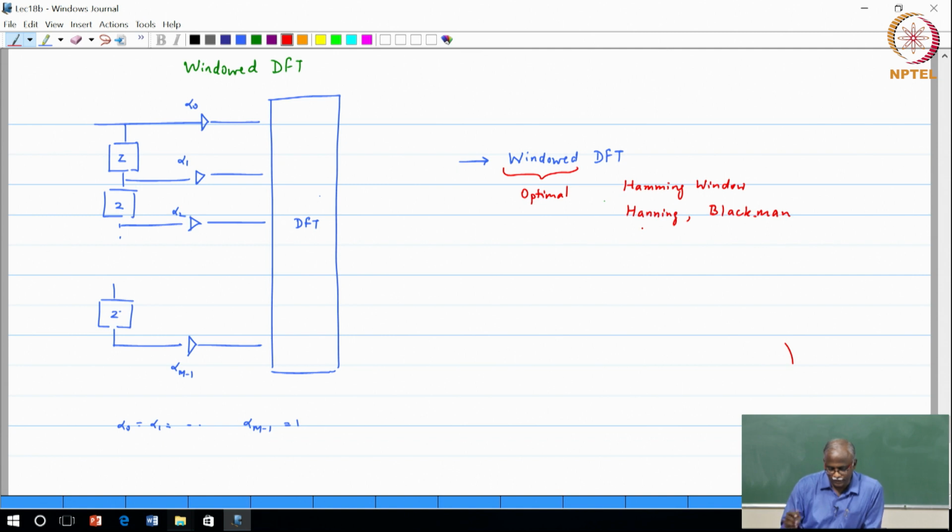So, that is what the windowing will do, but these are not the optimal windows. Actually it was shown that the optimal window is something called the Kaiser window. This is your optimal window. It tells you how wide the main lobe should be and how much attenuation you want. You can get even 90 dB attenuation on the side lobes, and the Kaiser window gives you a tool to design these windows, and this would be the right way to do it if ever you have to do a spectral analysis. And we also said that one is looking at the window.